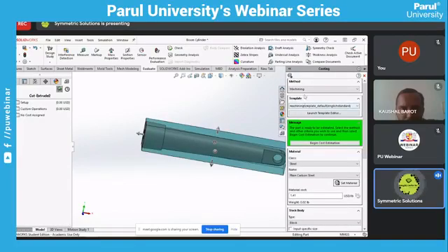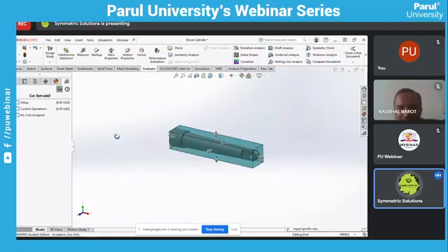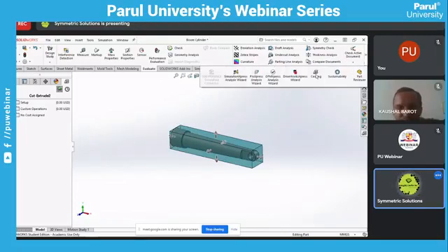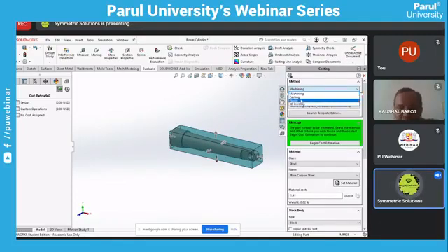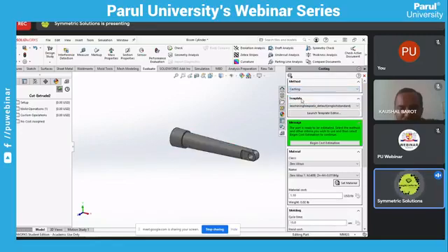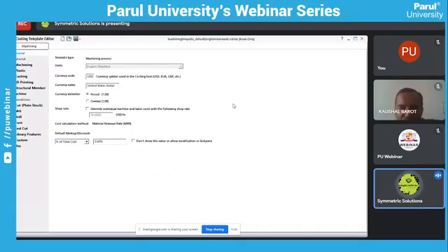In costing modules, define your method of manufacturing: machining or casting or plastic or 3D printing. Just select your manufacturing process. If we have to create this object from casting, then select casting, then define launch editor, means a template editor for cost report. Now currency mode is USD, just change it to INR, Indian Standard Rupees, right?